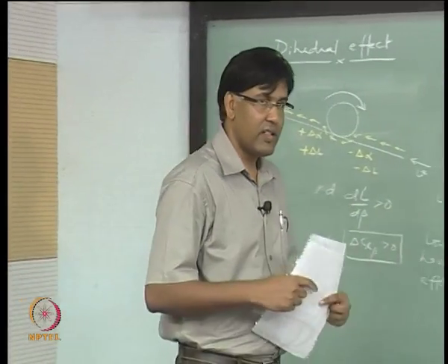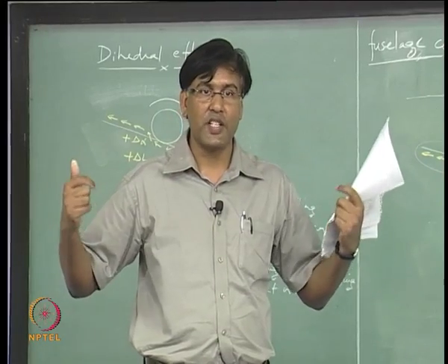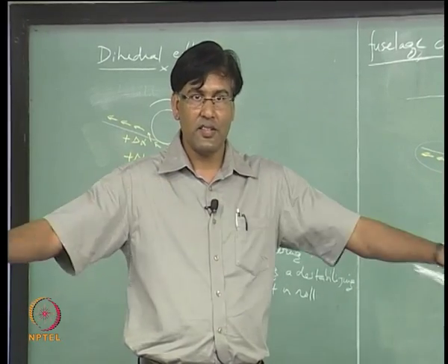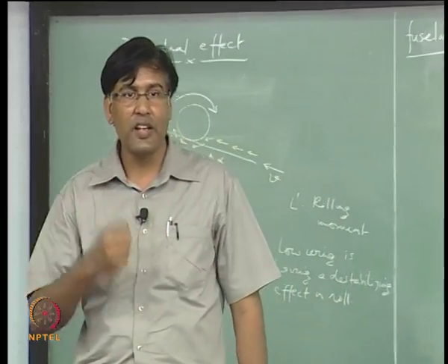There are three combinations actually, right. Many combat aircraft you see recent ones, you will see that it is high wing configuration with wing swept back and wings drooping down like this. It is a combination. So, all three effects are there.